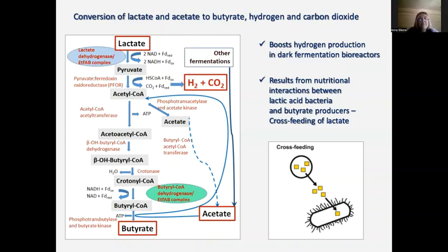Here you can see a simplified scheme of our 2-stage anaerobic digestion system processing byproducts of the sugar beet industry. As a byproduct, we use sugar beet molasses containing 50% of sucrose. One bioreactor is for acidogenesis to produce hydrogen-rich fermentation gas, and the second bioreactor is for acetogenesis and methanogenesis to produce biogas. We use this system for basic research to study microbial communities and metabolic pathways of biohydrogen and biogas production.